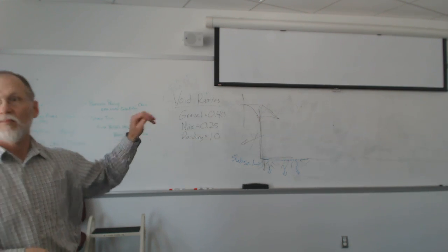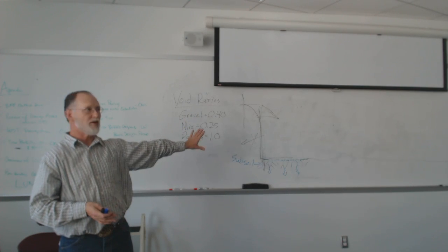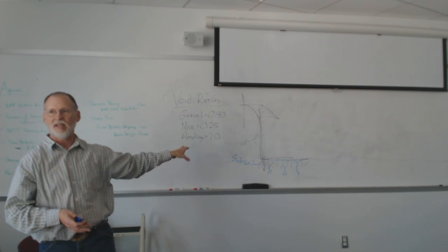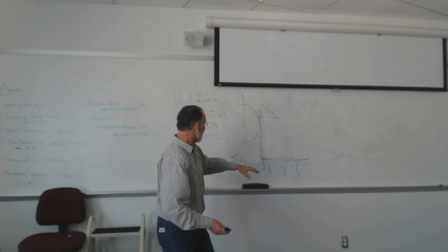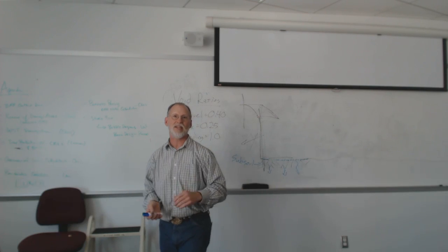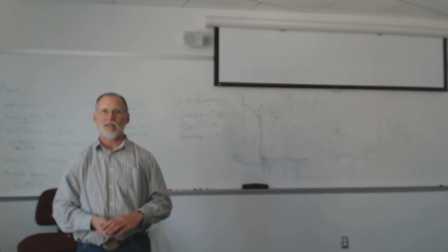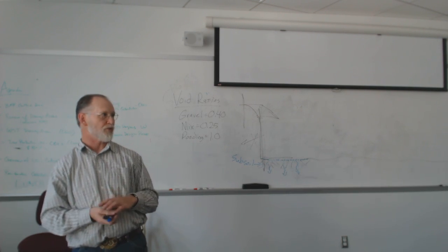Yeah, if we're doing under drains, that's different, but no matter where they're digging it, whether I'm going to have under drains or not, whether I've done my tests and my soils are crap or not, I'm still an optimist. There's no reason not to leave that surface nice and rough. There's no advantage to having a straight bucket and a smooth surface on that. It doesn't do anything good for you. So I'll still want that surface rough.